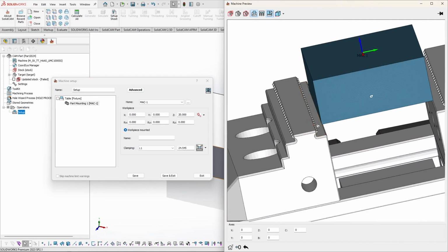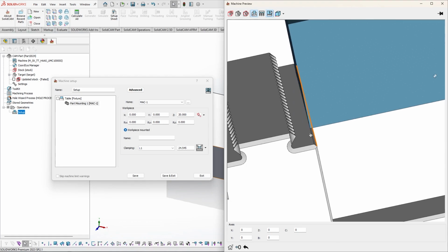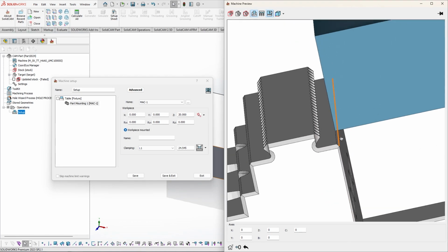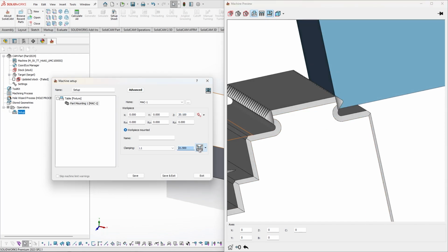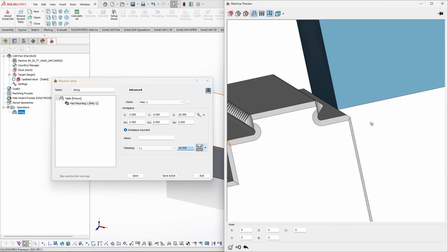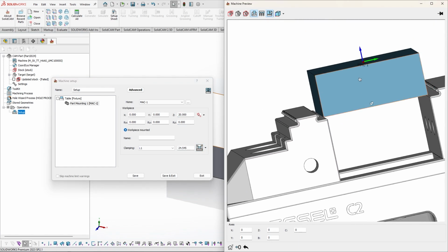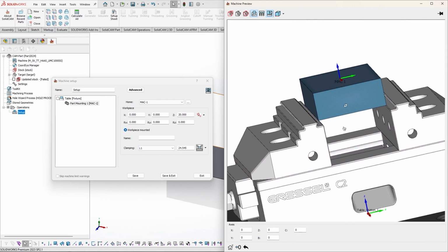Now, please be aware that there can be these kinds of situations, depending also on your 3D models. If you have a chamfer, it will get stuck on this edge here. You can lift it a couple of hundredths, and then it will work fine. In most cases and jaws, it will work fine. But there will still be, as I said, some strange jaws, especially with a desired shape of the part, custom made for those. Auto close will not work.